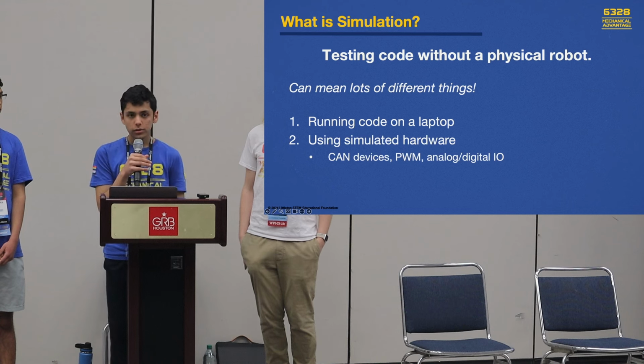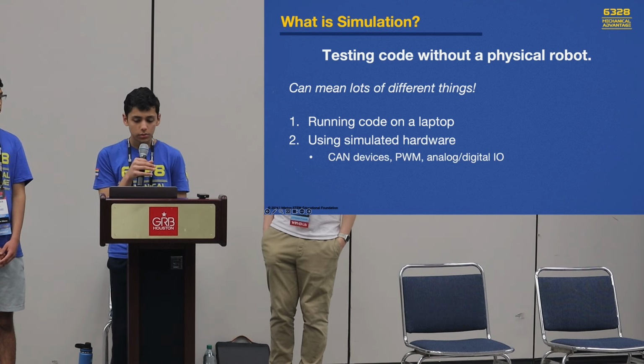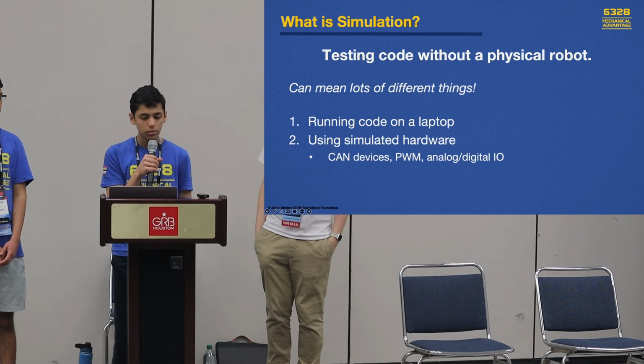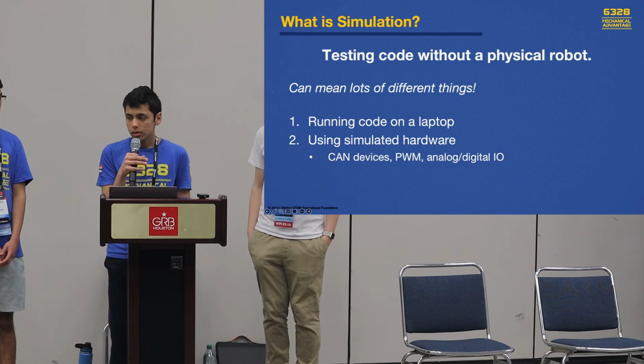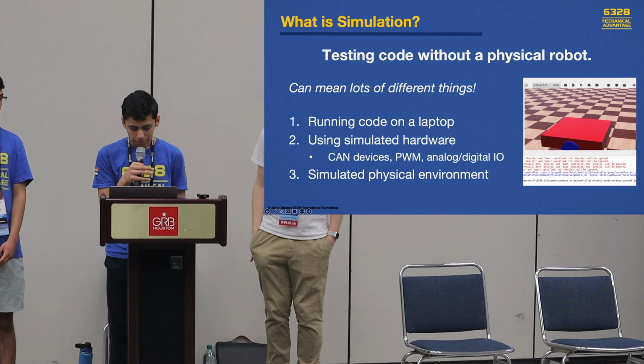It also might mean using simulated hardware, because we don't actually have the CAN bus or the PWM outputs that are on the robot. So we need some way to mock or completely replace the stuff on the robot so you can run it on our laptop.